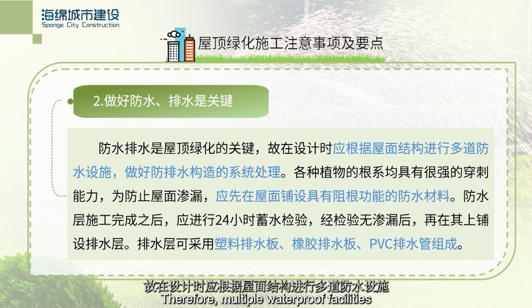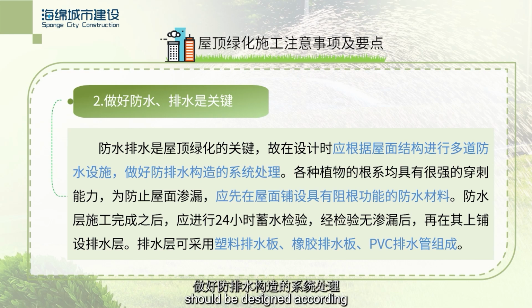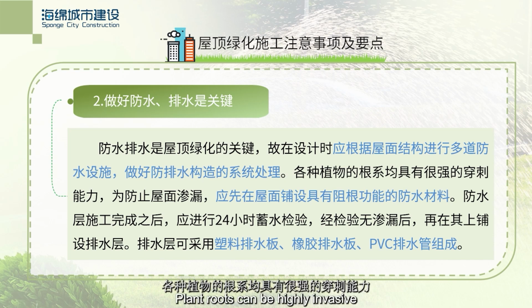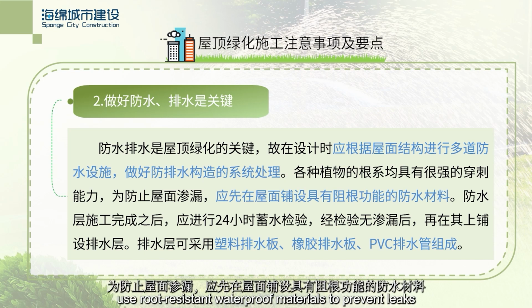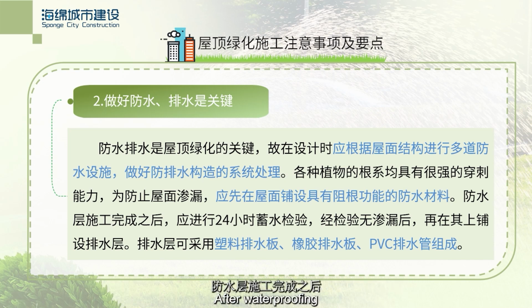Therefore, multiple waterproof facilities should be designed according to roof structure. Plant roots can be highly invasive. Use root-resistant waterproof materials to prevent leaks. After waterproofing, conduct a 24-hour water test to confirm success.